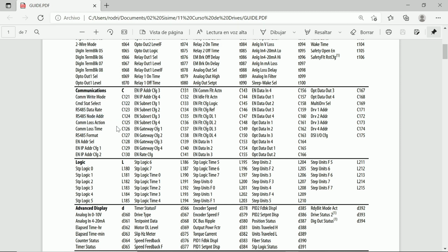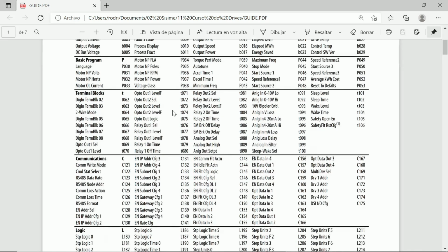What type for our node, just in case we have an RS485, or if we wish to configure our IP, we just add these parameters. If we want to add a subnetwork, then we modify these parameters. It says configuration number 1, we have our octet for my sub-configuration number 2. And so on.